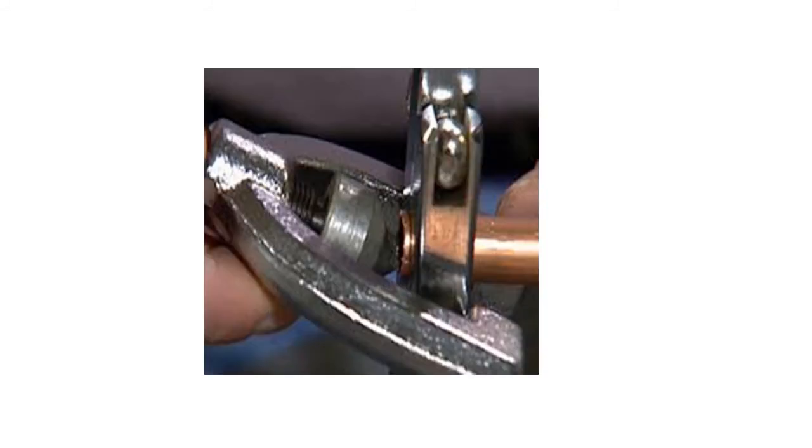Other methods of joining copper pipe are flares for soft copper and unions for both hard and soft copper. This is a picture of a flare being made with soft copper. A flare is a 45-degree angle formed on the end of the tubing, which forms a gasket when used with a flare nut.